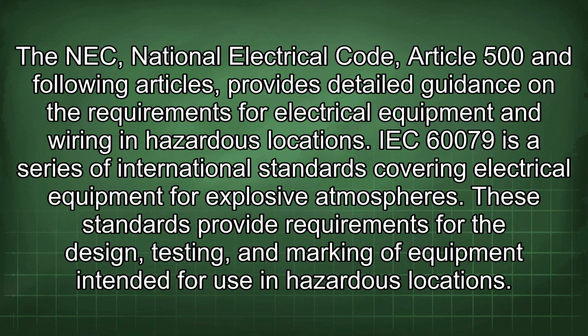The NEC, National Electrical Code, Article 500 and following articles, provides detailed guidance on the requirements for electrical equipment and wiring in hazardous locations. IEC 60079 is a series of international standards covering electrical equipment for explosive atmospheres. These standards provide requirements for the design, testing, and marking of equipment intended for use in hazardous locations.